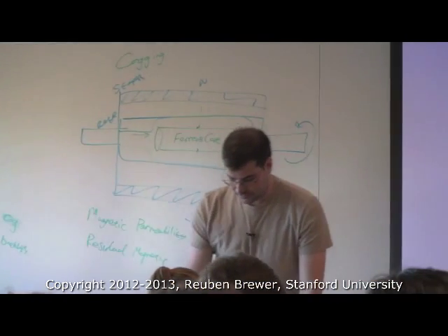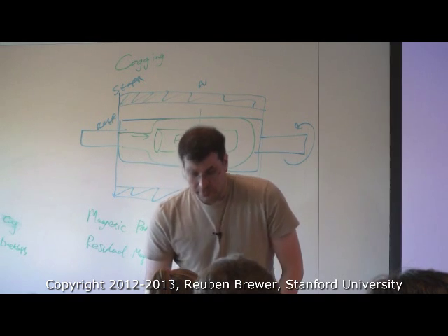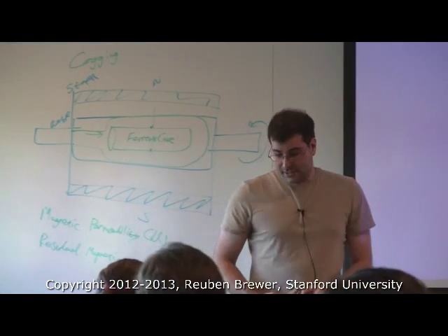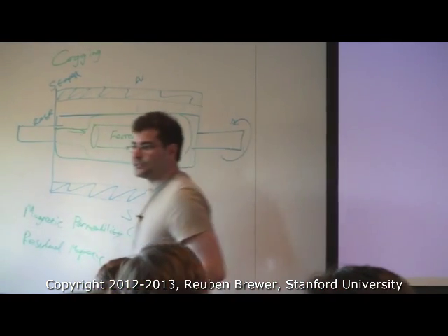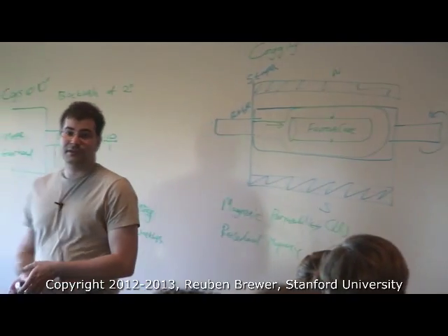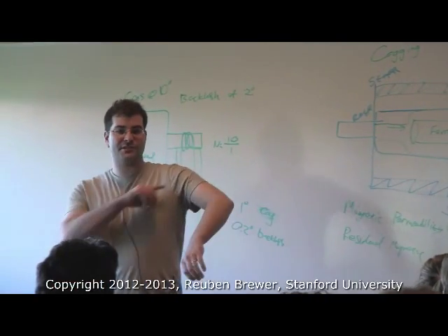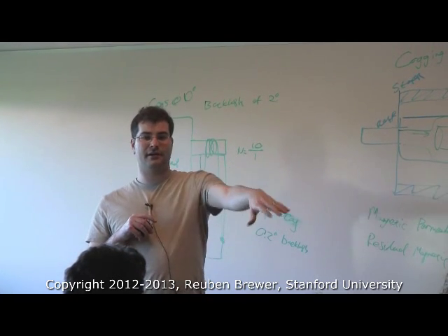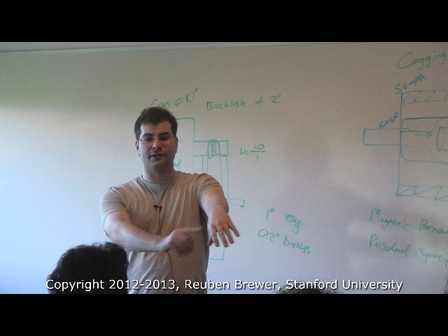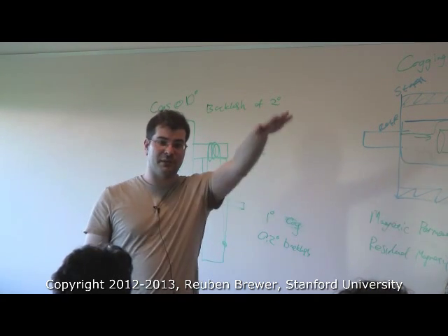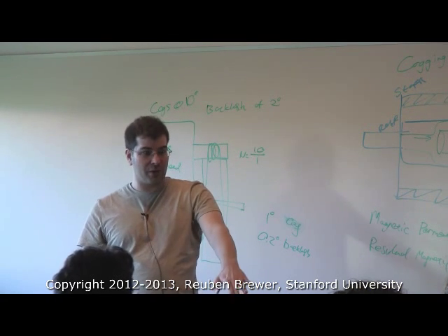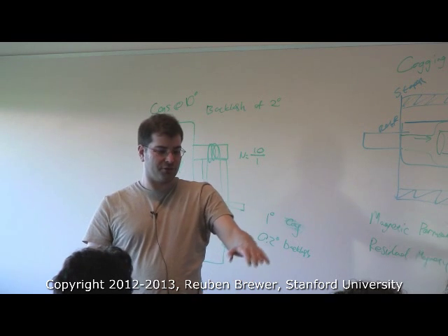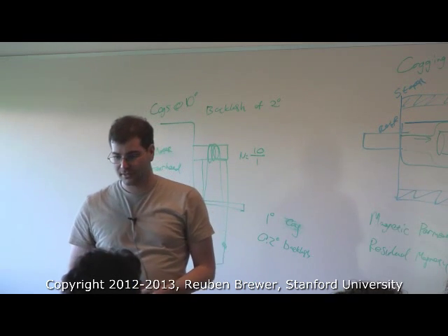But isn't that a trade-off, because you kind of said don't use cables unless you really need to? Yeah, and if you have nasty backlash in a robot arm, you often need to. The problem is backlash in a serial manipulator like this will kill you because it's the R dθ, and the R is high. So even for small dθ, you get huge error. When you watch robot arm movies and they're doing this, often that's backlash.